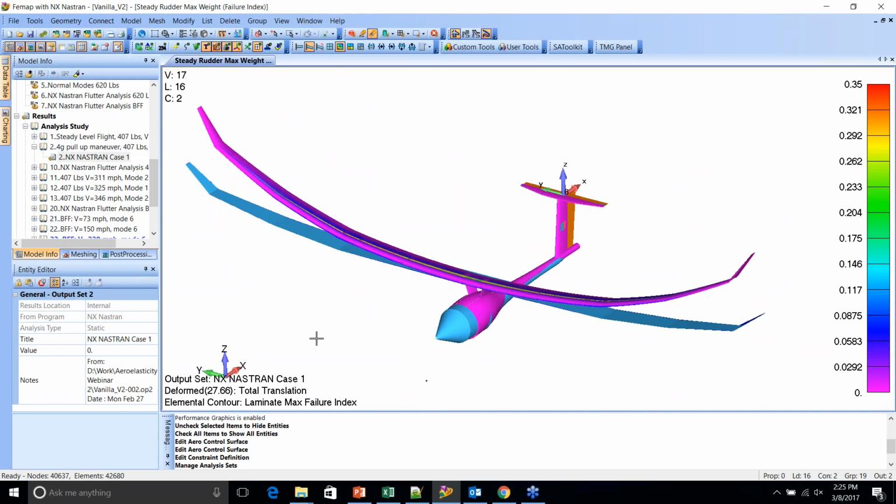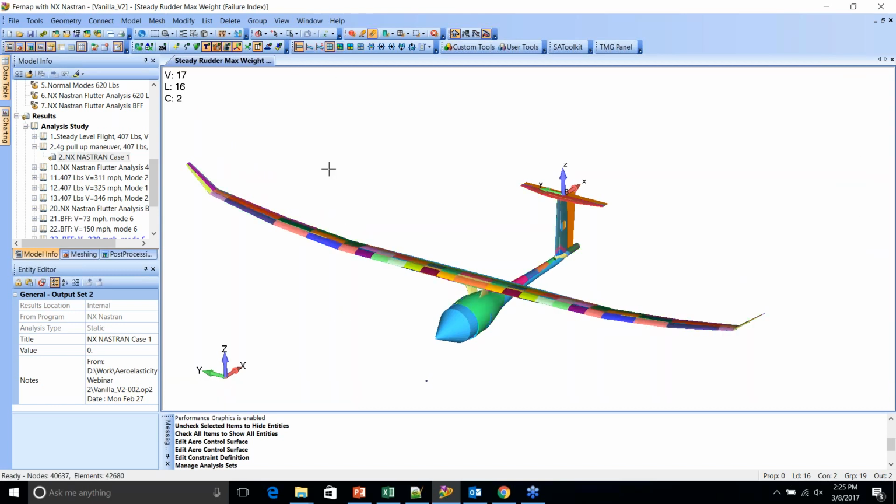Again, this is kind of a manufacturer problem example that I did on this model, but it gives you a really good idea as to how, without having any knowledge about what the loads actually are, we know very simply that our aircraft might be sized by a 4G pull-up case, for example. You can do banking and coordinated turns too, but you can set this information at a really high level and then allow Nastran to disseminate that information and spit out some really detailed loads and then, of course, stresses and strains on your model.